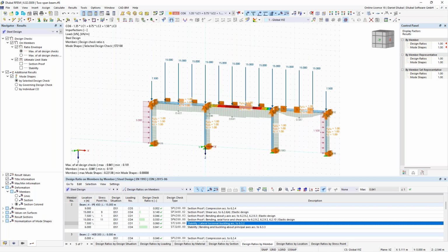And then we have performed two different methods. The last one was method B. And the first one is method C, so equivalent member method. And the equivalent member method is pretty important for your study because I did it a lot of time, and now I could show you how you do this also in RFEM 6.